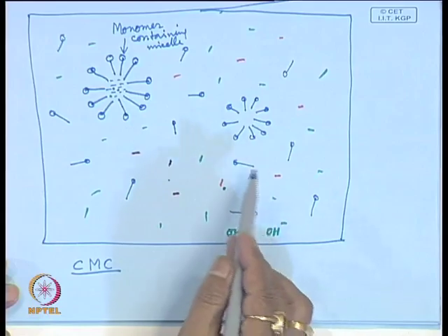Through the propagation step, that growing chain radical will grow bigger and bigger. As it grows bigger, what happens? It becomes hydrophobic. Once it becomes hydrophobic, due to the growth of this free radical size, it will try to phase out, come out of the aqueous phase. Eventually, soap molecules are there like friends, they will cover it.